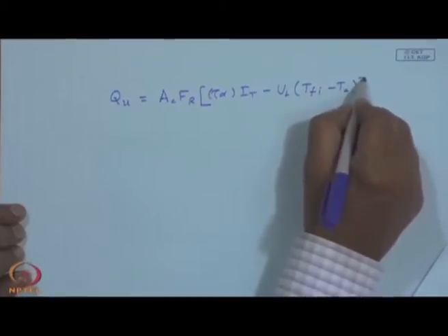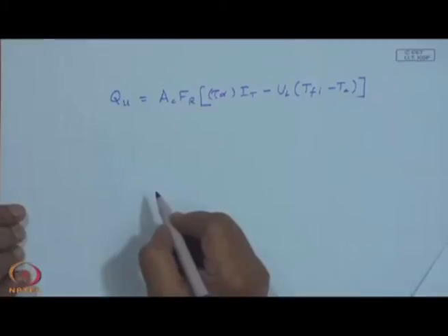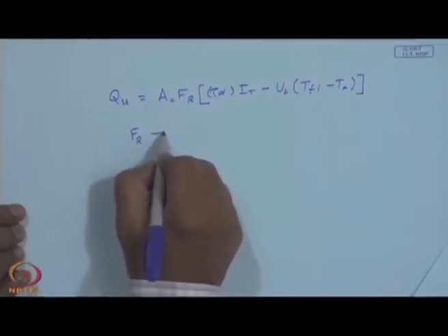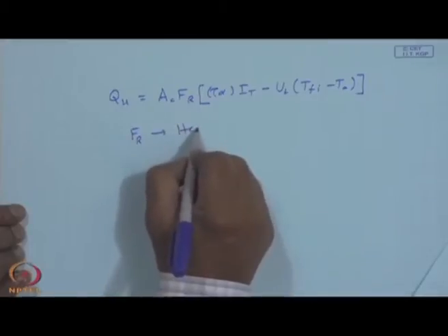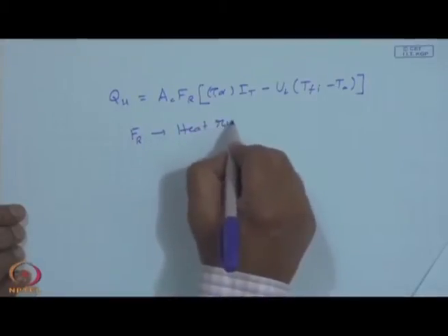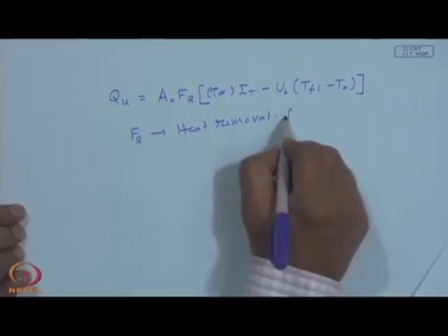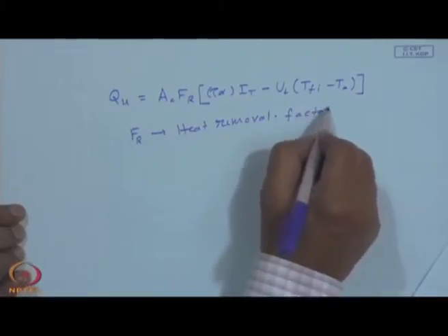So, there can't be any ambiguity about it, and the factor F r we already defined as heat removal factor, which is in a way analogous to your heat exchanger effectiveness.